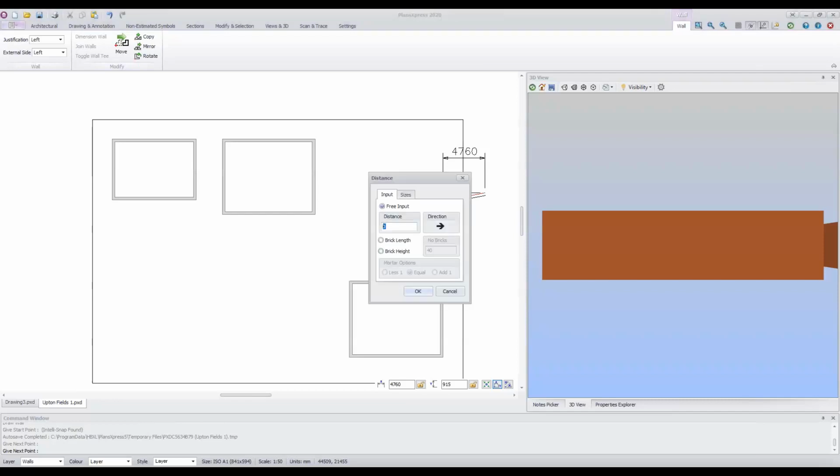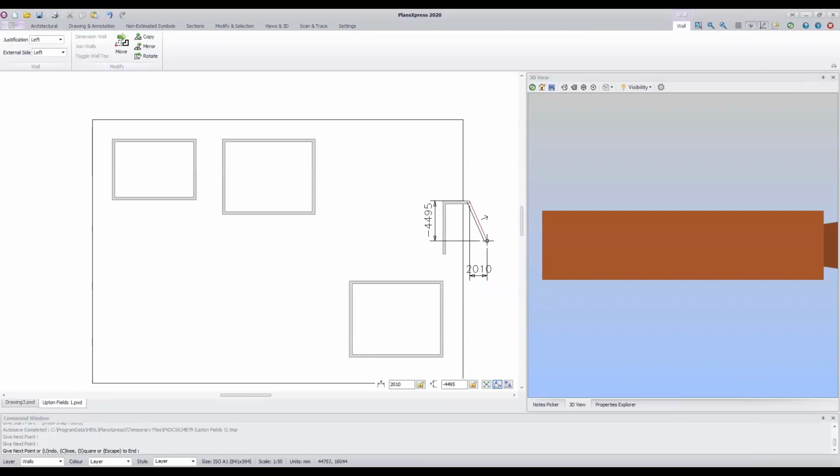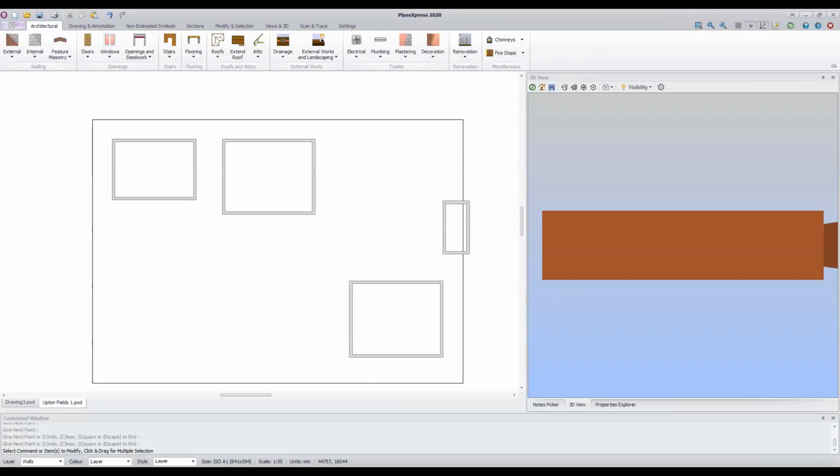And then let's say it's 3 meters wide. Type in the distance, click OK, or return, and then we could press the S key on the keyboard to complete that loop of walls. Okay, so the main thing there was we were using the R key to place a new point on the screen relative to an existing snap point on something that we've already drawn.